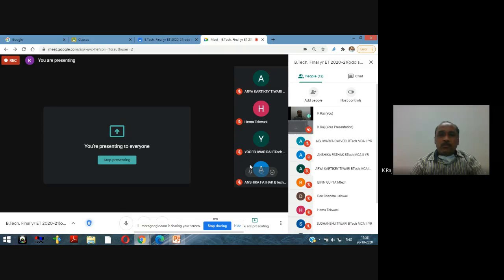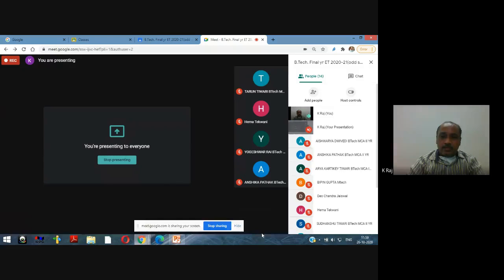These models were developed in the time domain. Then we also discussed how the developed mathematical model is transformed into the frequency domain using the concept of the Z transform. And we discussed the different possible architectures or realizations of the developed mathematical model. Then we described the design concept of the FIR filter and the IIR filter.